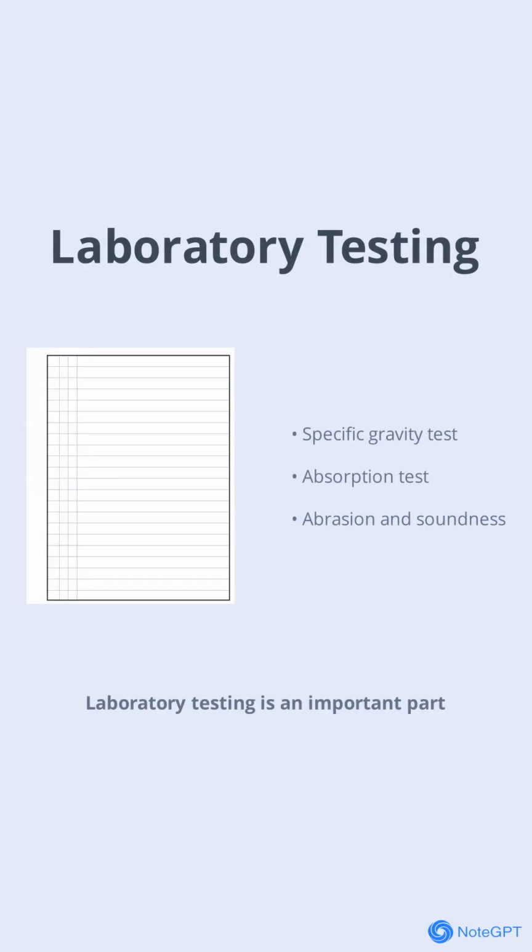Laboratory testing is an important part of quality control in rock fill construction. Common tests include specific gravity, absorption, Los Angeles abrasion, and soundness tests. These tests help to determine the physical and mechanical properties of the rocks, ensuring that they are suitable for use in construction. Laboratory testing provides valuable data that guides material selection and construction method.